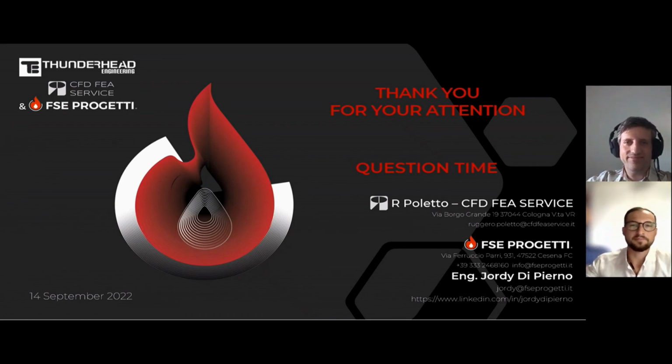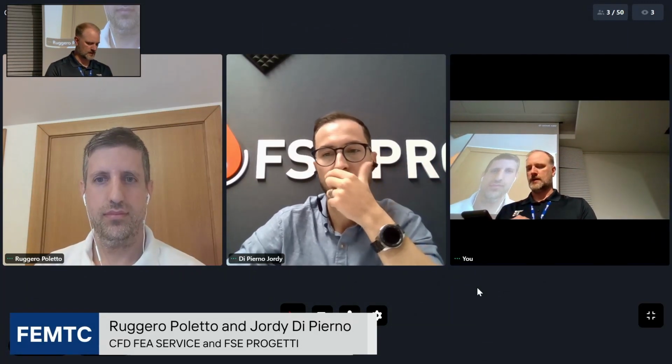Okay, great. So we did have a question here. Just for the audience, regarding the paper factory, which is the reference scenario in terms of heat release rate for each of the cases you mentioned, did you consider experimental data coming from available full-scale tests? It has been demonstrated that the layout of the fire load, the height of storage, the free space among fire loads, et cetera, play a fundamental role in the resulting heat release rate. And I do see the experiment for tissue paper heat release rate. The other issues, like layout, height of storage, free space between the fuel loads, were those considered in the work?